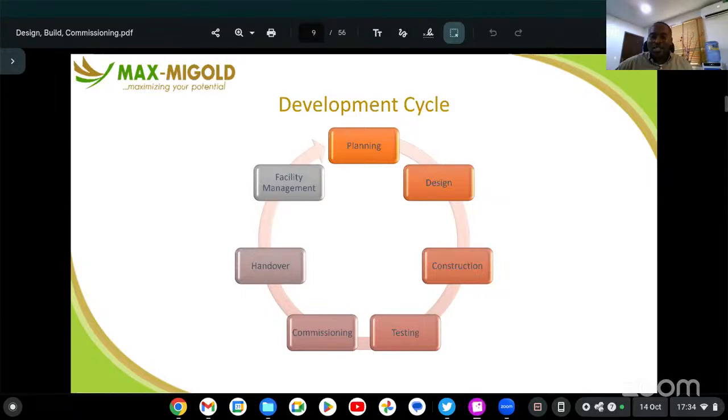After all checks have been done, you say, okay, it's now fine. You check again and see that the voltage is now probably 218. Okay, that's nice. Or 222. Okay, that's nice. Then you energize the breaker so that the master breaker now serves each component inside the electrical box. Then you check the contactor. If you want to use fuses, you can also use a fuse. You check the fuse and see that everything is fine and okay.